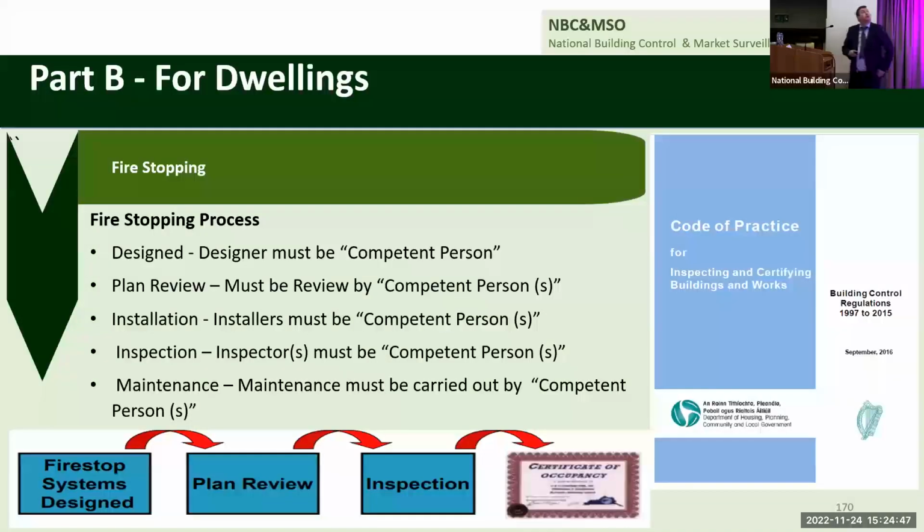Timber frame manual. So fire stopping: the designer must be a competent person. He must plan and review, and plan where he's putting it in, what he's going to do, what products he's going to use, are they compliant, are they going to be fit for purpose.